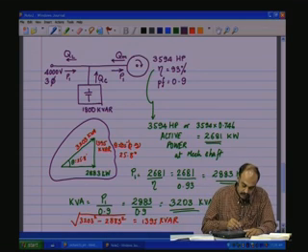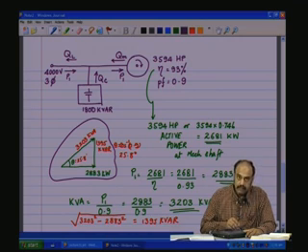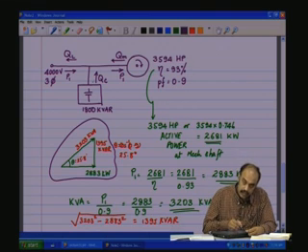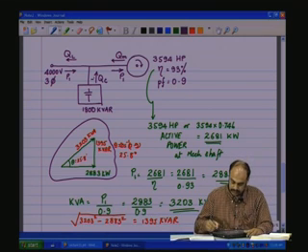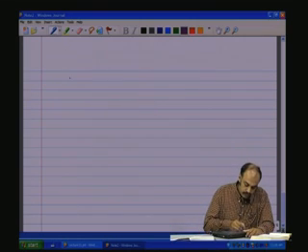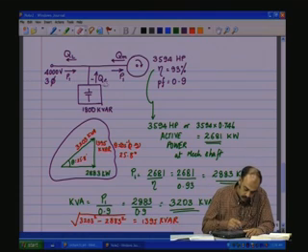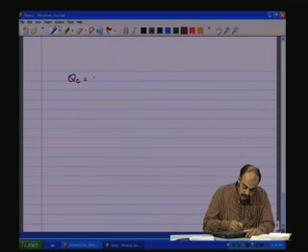So, you see that QC we are showing in this direction, but actually this is a passive circuit. If this is an 1800 kVAR reactive circuit, passive, this is not a generator, so QC, now pointing in the other direction, is minus 1800 kVAR.